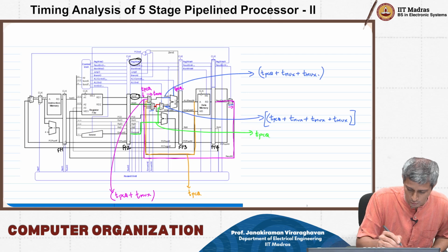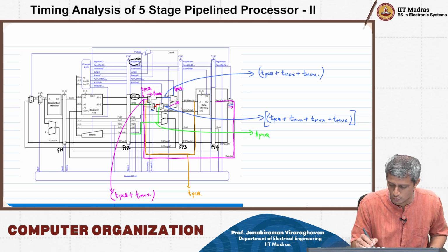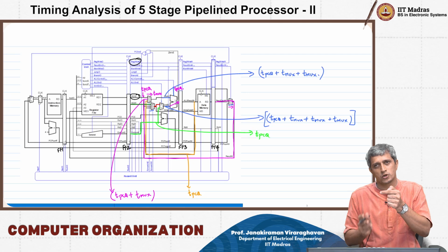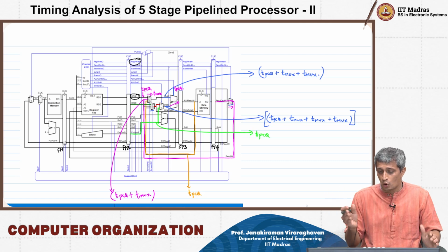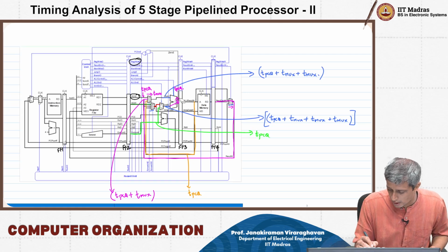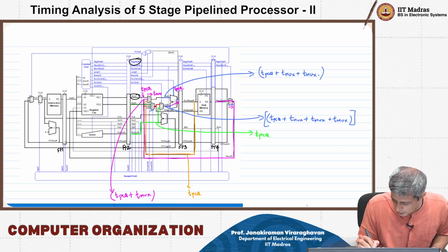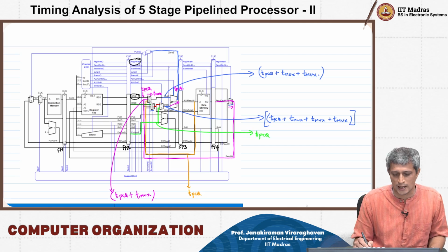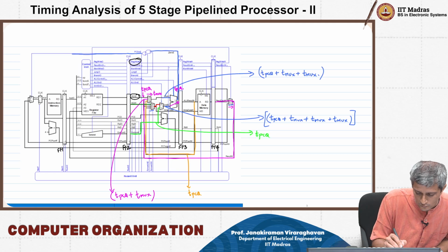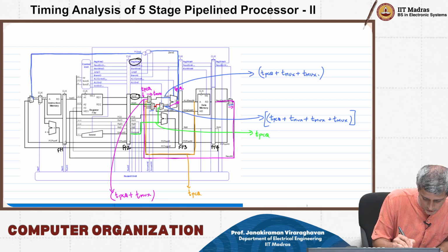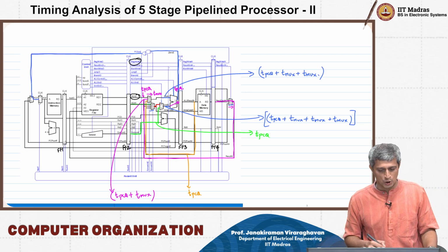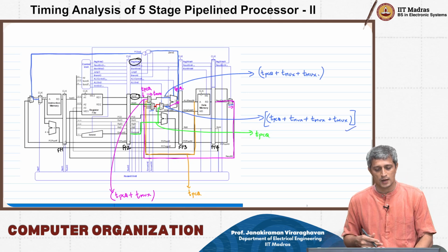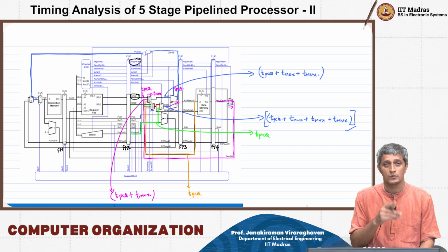So if you look at this, I am going to now go through this TALU, okay? Now the TALU output goes directly to flip-flop 3, okay? So technically you would think that is the critical path, but note that there is a 0 flag here which is coming out, right? So therefore if you trace this particular path, something very interesting happens. You are going through this AND logic and OR logic, coming back here through this mux back to the PC, okay? So the ALU output would have been ready after this much delay, TPCQ, Tmux plus 3 Tmux plus TALU, right? That would have been ready.